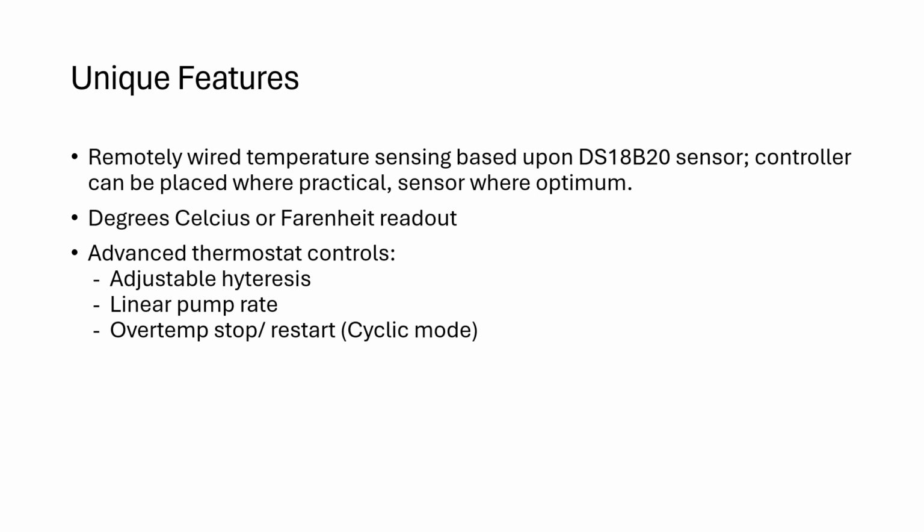Typically that is something that's used with the linear hertz mode, which means that as the set temperature is approached, the fuel delivery is reduced along with the fan speed. So how I have mine configured, for example, if the temperature is set to 70 degrees, as the interior temperature approaches 70 degrees, it will reduce the heat output and try to maintain it at 70 degrees.